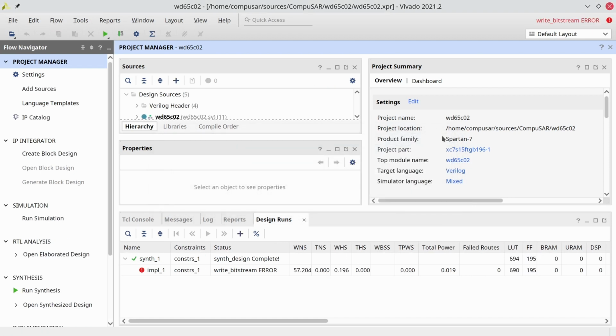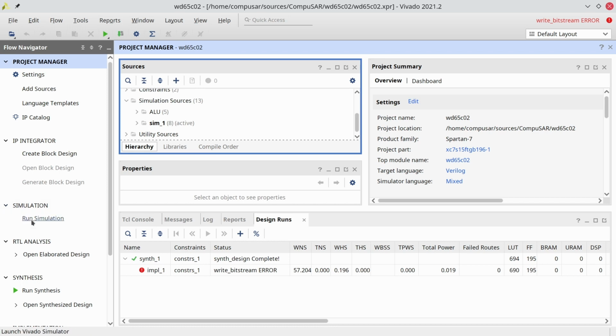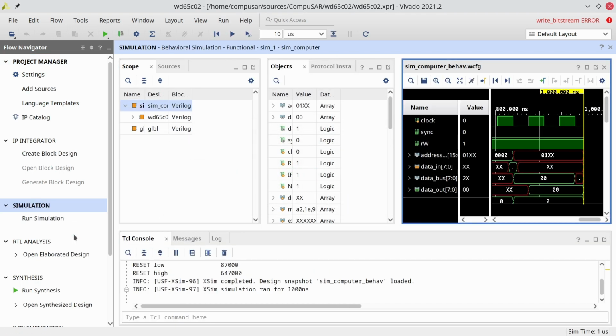The first thing we need to do has nothing at all to do with implementing the opcode, in a way. The first thing we need to do is set up the simulation. Pretty much any FPGA and even any hardware development platform has a simulation mode. In the simulation mode, we can take the module we're building, hook it up to a simulated circuit, and see how it behaves.